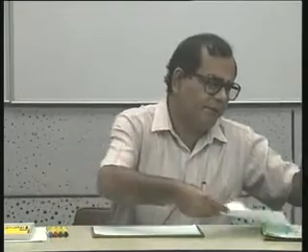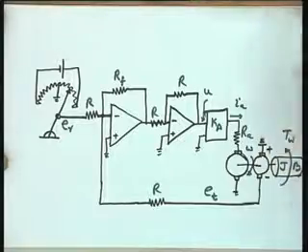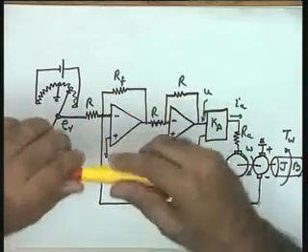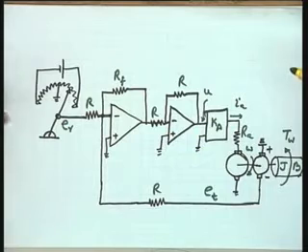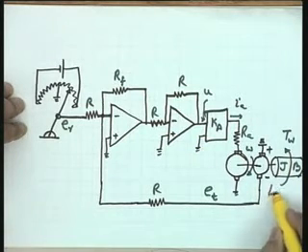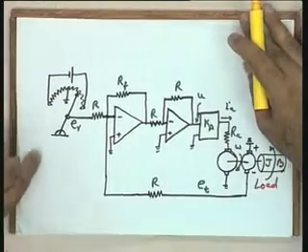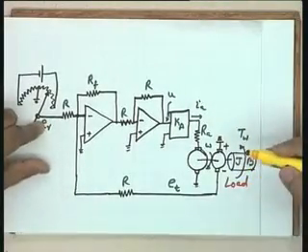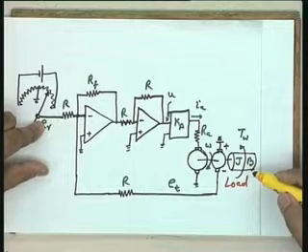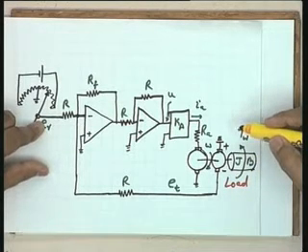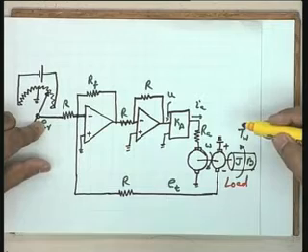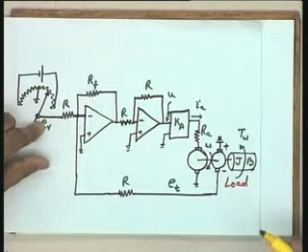I take up the first control system as a speed control system. This is the speed control system, and now you see how the system works and what the basic ingredients in this particular system are. In this case, you want to control the speed of the load. So, here is a load, the parameters are J and B, the moment of inertia and the viscous friction B. Tw is the load torque on the system, that is, it is a disturbance torque acting on this particular system.